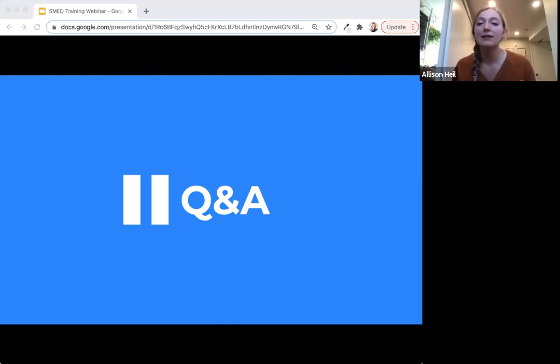Generally, they say in a SMED event, though, you should be able to cut your changeover by at least 50%. So the theory is that if you have a changeover of an hour, and you do one SMED event and you get it down to a half hour. Okay, great. We're looking good. We're sustaining. Let's do another one. So you do another one and then you get that down to 15 minutes and then you try to sustain that for a little bit. And then you do another one, right? So you just repeat this cycle of trying to always aim at least a 50% reduction.